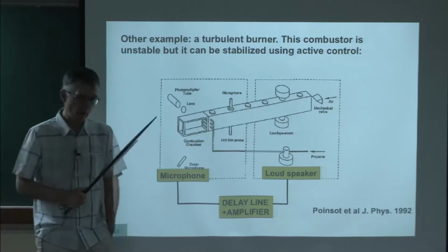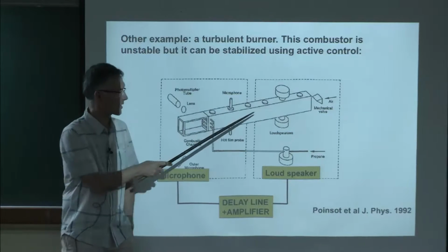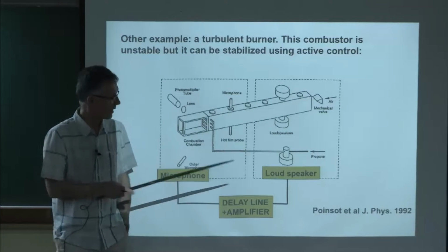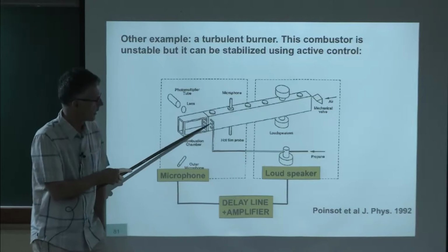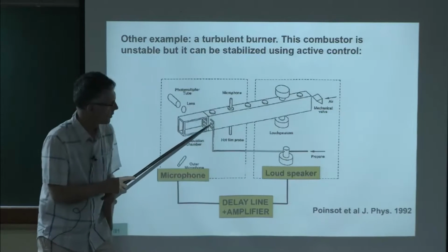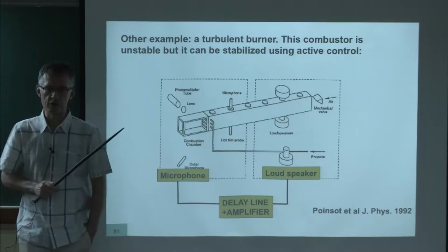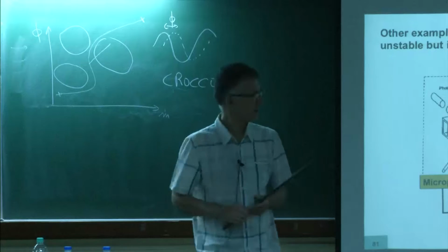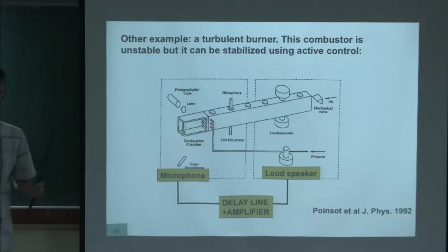here, in a system like this, which was a diffusion flame, the smart thing to do is not to excite the air, because that's a big flow rate, but just to excite the fuel. So we are actually pulsating the fuel injection, and only the fuel injection, which is like 20 times less than the air. So you can use much smaller systems.